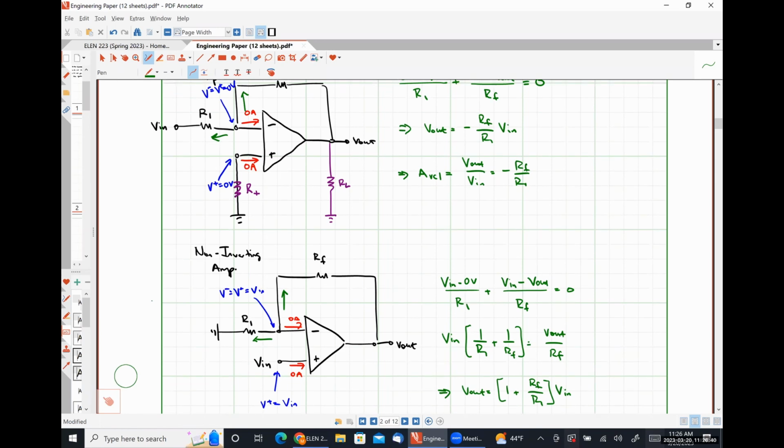Yeah, so at the non-inverting input terminal for the non-inverting amplifier, we have Vn. For the inverting amplifier at the non-inverting input terminal, we have ground. So the only difference between these two circuits is literally us swapping those voltages, right? We move ground from the non-inverting pin to the leg of the resistor R1. We move Vn from this leg of resistor R1 over to where ground was. It's literally just swapping those two voltages.